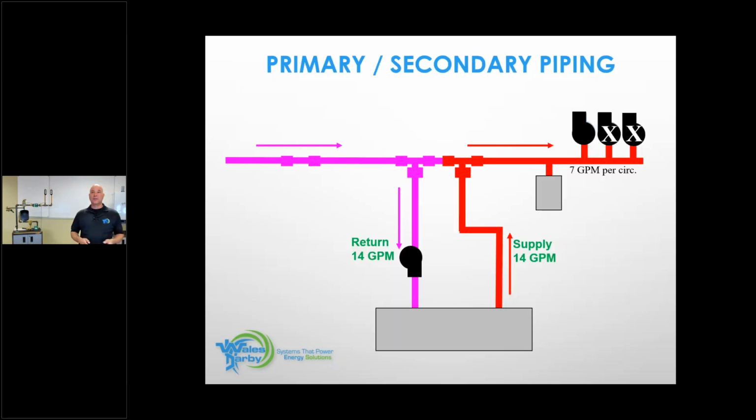Now let's get into something that may be a little more realistic for what you do on a daily basis. At the bottom of this PowerPoint photo here, this is a boiler. Week 1, week 2, universal hydronic formula. I'm just going to assume a 20-degree delta T. Who can tell me the size of this boiler based upon the flow rates that you see right here on the boiler piping? If you need to remind yourself of the universal hydronic formula, that would be page 48.